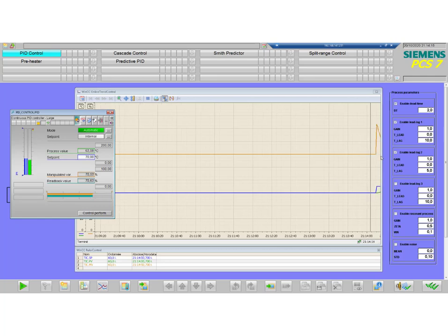So what you can see here is the proportional kick and derivative kick. Since we have a derivative time constant of 5 and this diff gain of 2, the derivative action is maintained for 5 over 2, so 2.5 seconds, right? And what you can see is a bit of integral action over here, but as you can see here, with this tuning of the PID controller, we have a very nice response.